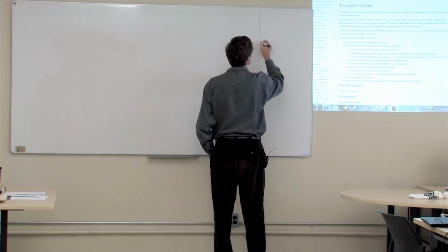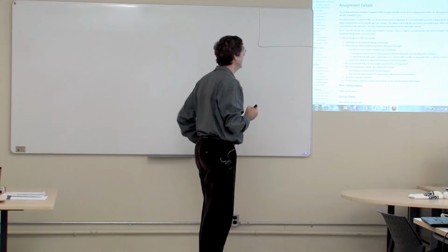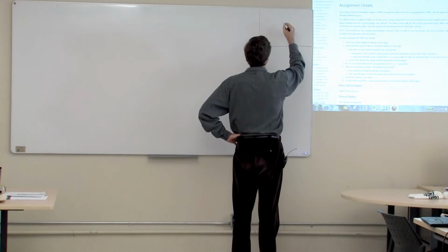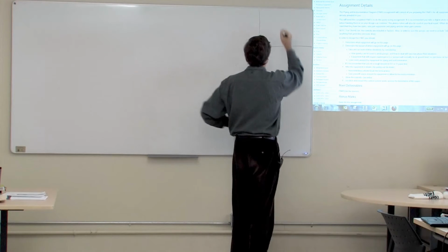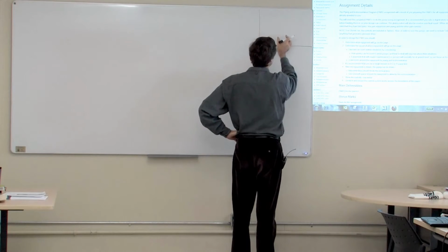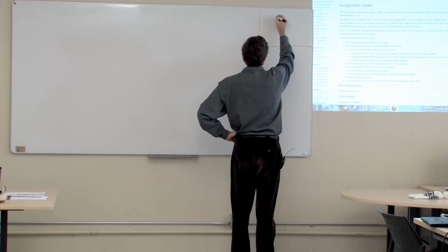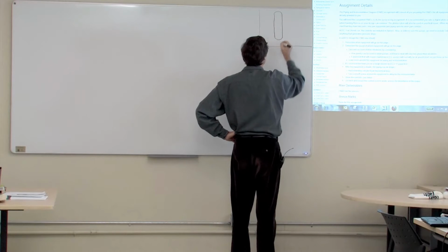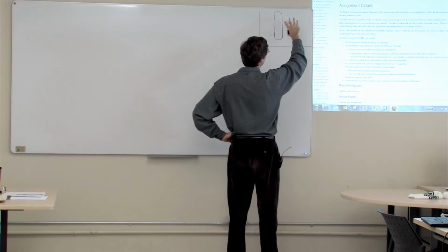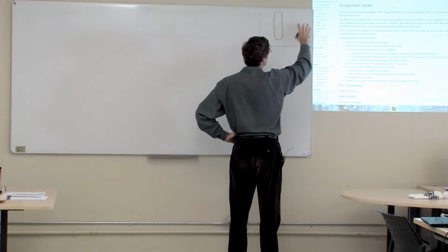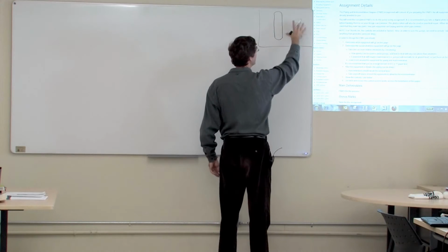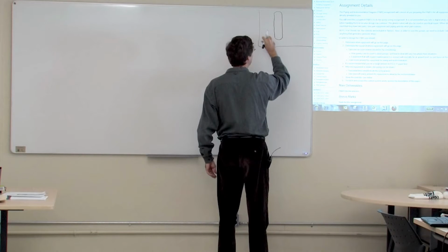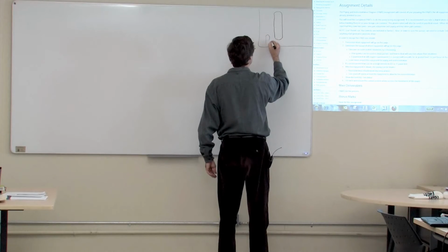Let's just draw a little tiny version up here and get a sense of the layout. It makes sense that we want to go from left to right. We're going to have our distillation column either in the center, or maybe you want to put it off to the right, but I wanted to put it a little bit left of center, because I'm going to bring my flows that come off the tower and the equipment down into this region here. But because I know I'm going to start to block myself out in here, I decided to put my reboiler in here.